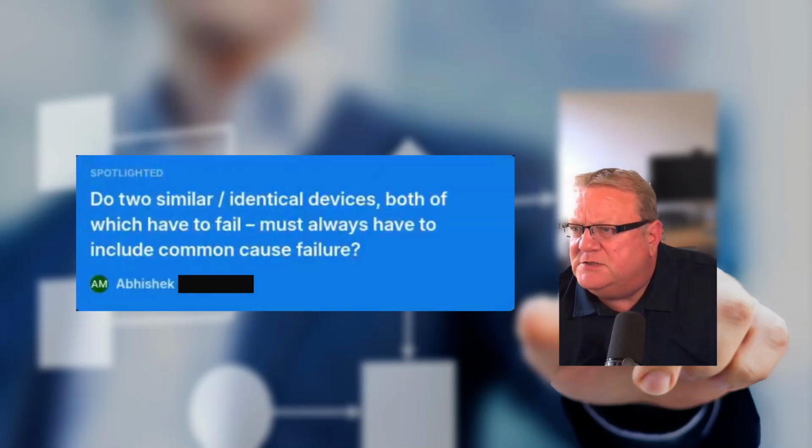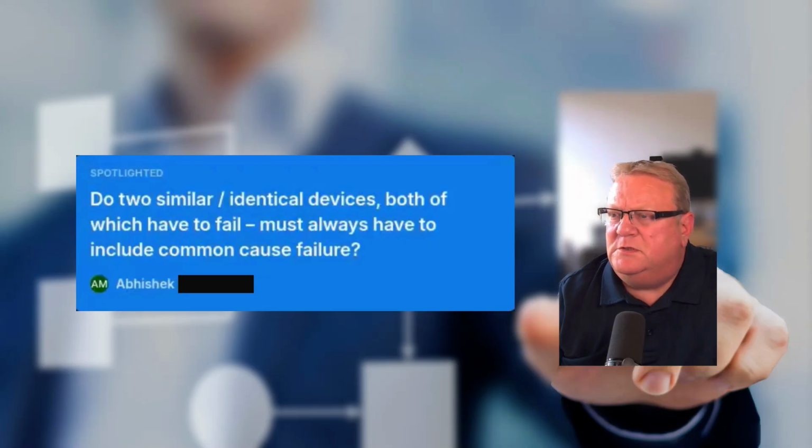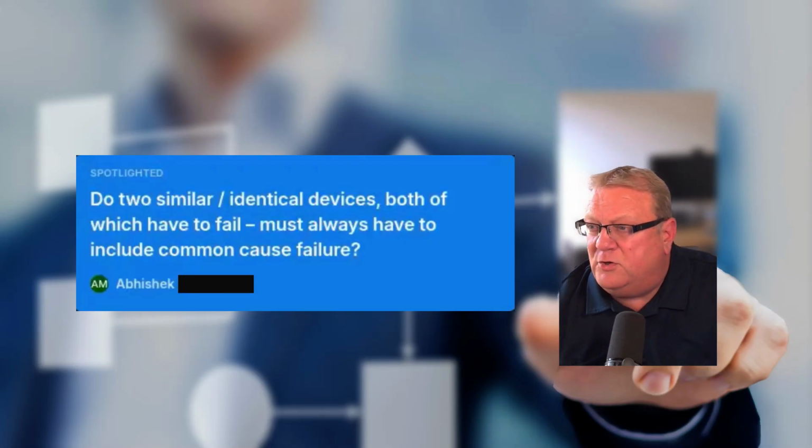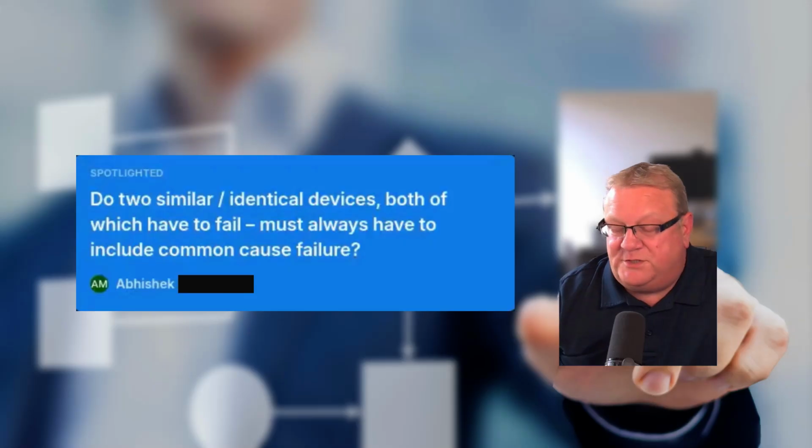Do two similar identical devices, both of which have to fail, must always have to include common cause? Yes, they always have to include common cause. You could say the common cause number might be lower if they are non-identical, but even if they're non-identical, there may be some common elements, common causes, but the common cause number would be different. But yes, you always have to include common cause if they're identical devices. You did say identical devices. Yes. So whether it's two valves, two sensors, two redundant I/O cards, it doesn't matter what they are.